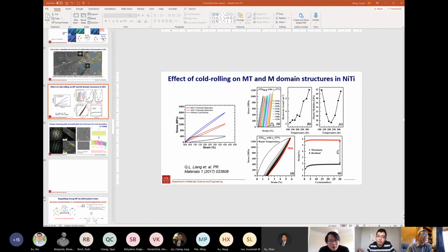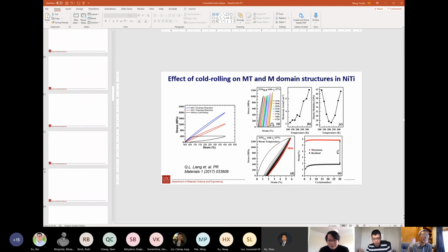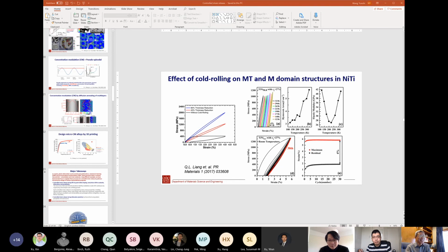That's very nice. I just have another follow-up question. If you think about additive manufacturing, like a laser powder bed, the cooling rate is very high, and normally we see a lot of martensite already because of rapid cooling. Do you think we need to use more beta stabilizer to get a metastable BCC despite the rapid cooling? Otherwise, if you transform a lot from BCC to martensite, we have very high strength, but we could lose a lot of ductility.